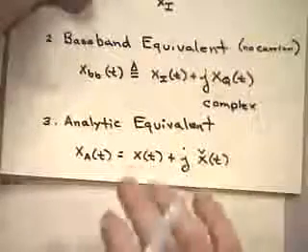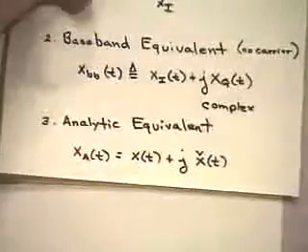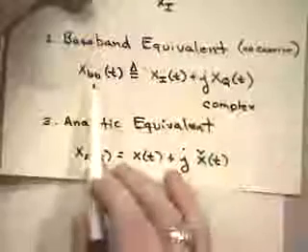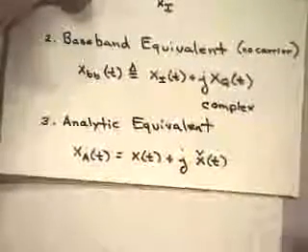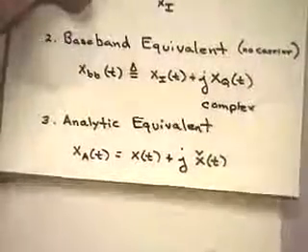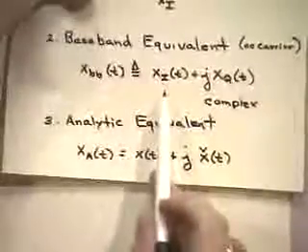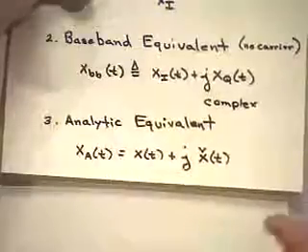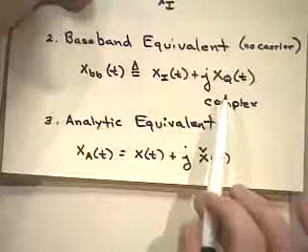Okay, we're going to find a nice, easy way to take a channel later and figure out what's really going on in an equivalent baseband analysis so that we can take our modulated signal we've defined here and convolve it with some equivalent channel and not have to worry about carrier frequencies anymore. So we're headed that direction. It's real easy for the modulated signal to get this baseband equivalent. For a channel or something else we're dealing with, it may not be so easy to pull out the in-phase and quadrature parts of the channel.